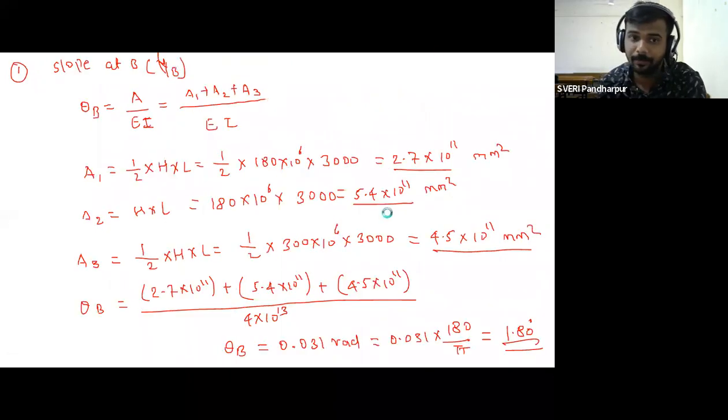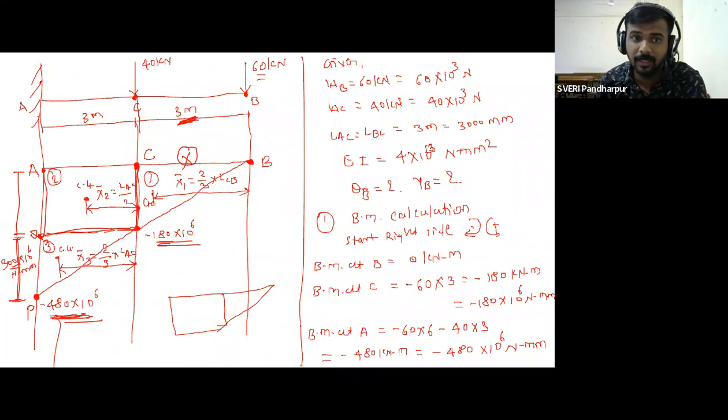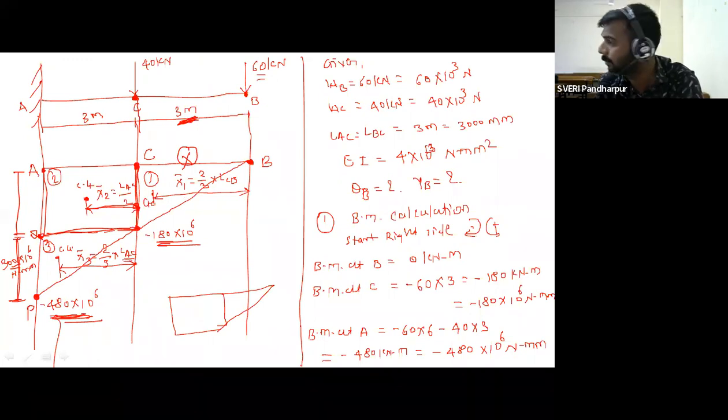In the figure, for the deflection calculation at point C, directly I am taking this x2 bar distance up to the point C only. So what will it be? L divided by 2. Is there any need to add the 3000? No. Similarly for the third section, 2 divided by 3 into length AC. Again, do we need to add 3000 in this?